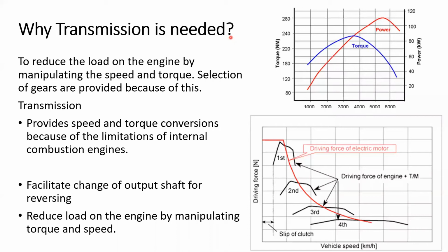PWM is applying and turning the motor on and off in time intervals in order to provide the power and turn it off. By doing so, we can control the torque at the level that we need, right? That's actually done by a control module inside the electric motors. So we just apply the accelerator, but the system itself controls that.